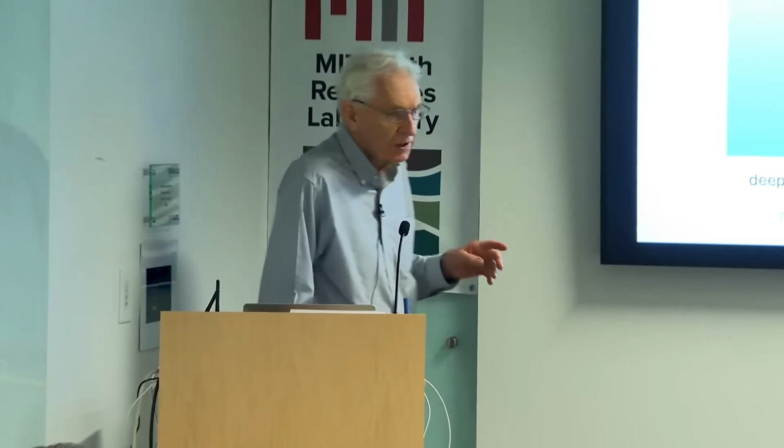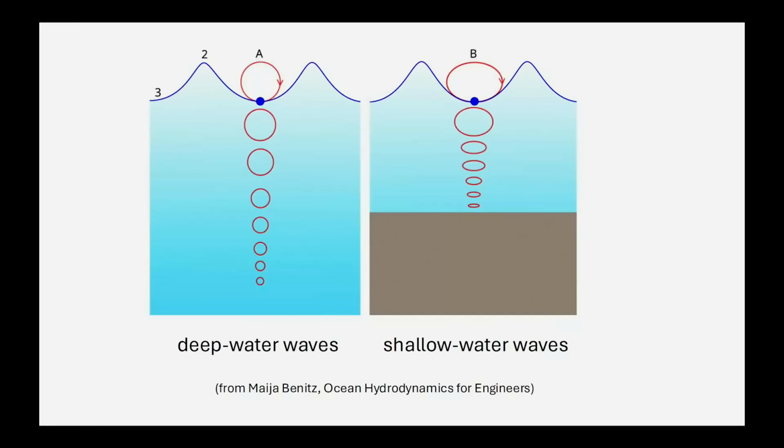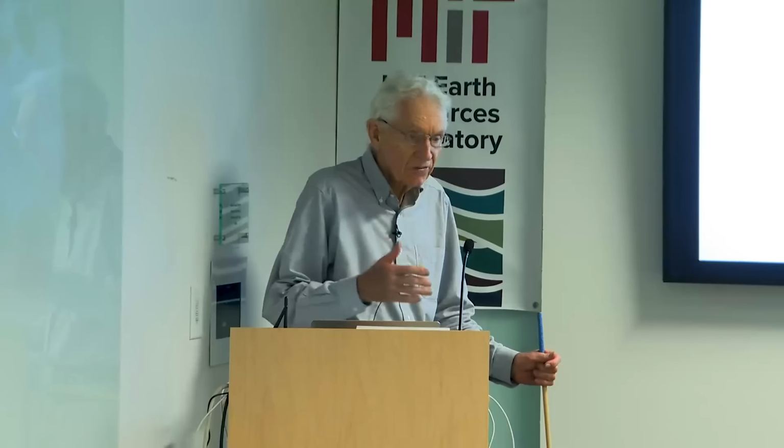But there's an important difference between deep water waves and shallow water waves. In a deep water wave, the seabed is so far down that the orbits die out slowly with depth. They disappear before you reach the bottom. And that's not relevant to our business here. But with shallow water waves, the orbits are ellipses, and I can't tell you why, but they're ellipses. And the ellipses die back, but there's still back and forth motion right at the boundary, even at the solid boundary, at the seabed. And so that's relevant to us. We're going to think about how sediment is moved by oscillatory flows.